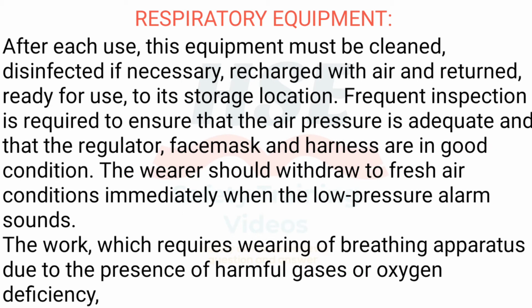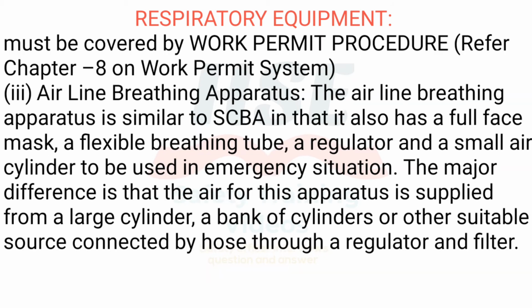After each use, this equipment must be cleaned, disinfected if necessary, recharged with air and returned, ready for use, to its storage location. Frequent inspection is required to ensure that the air pressure is adequate and that the regulator, face mask and harness are in good condition. The wearer should withdraw to fresh air conditions immediately when the low-pressure alarm sounds. The work, which requires wearing of breathing apparatus due to the presence of harmful gases or oxygen deficiency, must be covered by work permit procedure, refer Chapter 8 on work permit system.